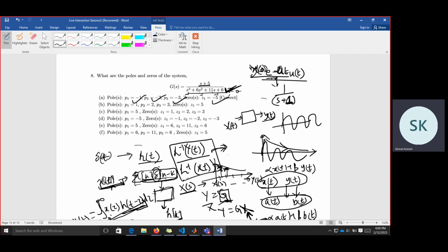So suppose that there is this pendulum. Now we are approximating this pendulum, meaning linearizing it about this equilibrium point, because this pendulum had two equilibrium points: at this location and an upright location. So it's angle zero, velocity zero, and angle pi, velocity zero, these two. Now this equilibrium point, if we see, this is a linear system.